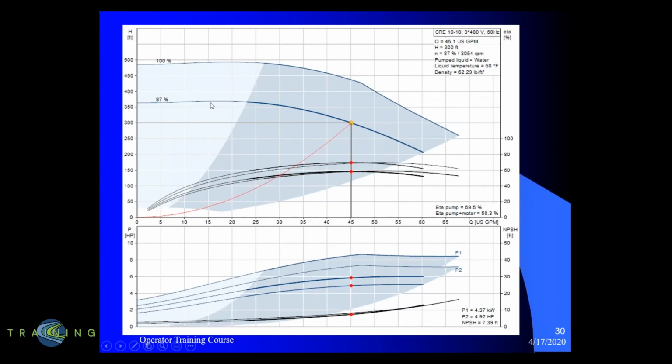This is our pump performance curve, and where the two intersect is where your duty point hits. So as we're designing with flow, calculating our head by using our system curve and applying the pump performance curves, we find the place that fits the best in our application to pick a pump from. And this is true in water and sewer. The same ideas are in effect.